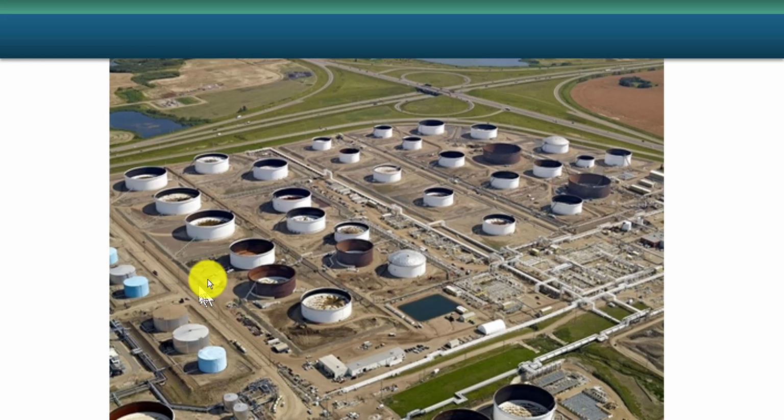The coating that's used on the shell is subject to much less abuse than the coating that's used on the horizontal surface, where you have direct radiation from the sun as well as ponding water that sits around a good percentage of the year. So this really should be a better immersion service coating, whereas a shell can be a cheaper typical exterior coating system. It's like your car. You can always see that the polish and coating deteriorates on the horizontal surfaces first, and then the side usually stays good, and you can keep polishing that forever.